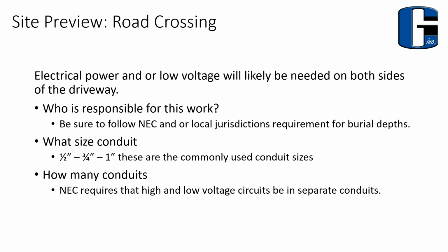How many conduits? Well, make sure that when you're doing a road crossing, you need at least 2 conduits put in, one for high voltage, one for low voltage. The standard says, and the electrical industry always says, separate high voltage from low voltage.